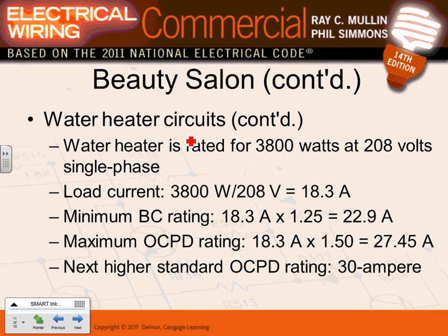A few things about the water heater. This is a really nice calculation if you guys just look at it. Here's the amount of water heater they bought. Here's the voltage. I want to remind you, Jeff and Jeremy, my friend, it is single phase, 208 single phase. Can I have 208 single phase? Yeah, 2 hots. So when you size, here's the watts for the heater. It's an appliance. When you size the service for it, you just divide it by the voltage. No 1.73, right? 13.8.